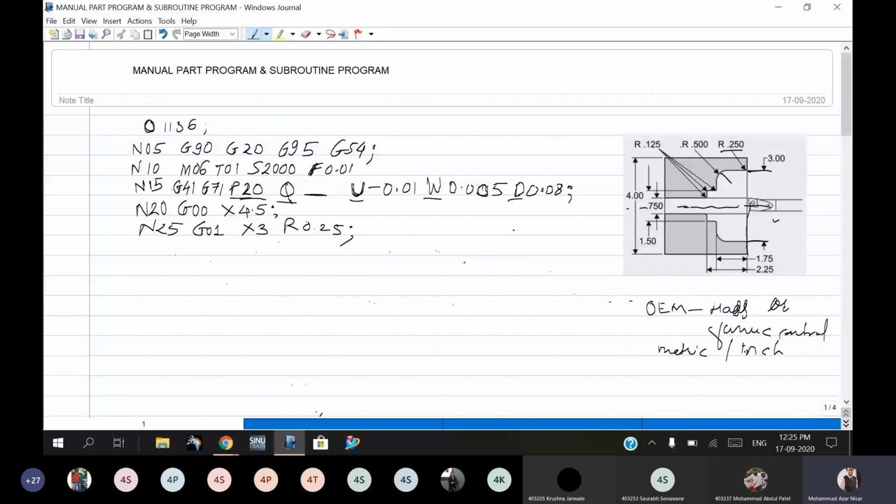Okay, in this line the spindle start line is missing, so you have to write down here N11 M03, that is clockwise direction, and M08, sorry, 8 for the coolant on. Okay, so this will be included in this cycle. This line will not be included in this cycle, because we have specified that our cycle is starting from P20. Okay, so next N30.